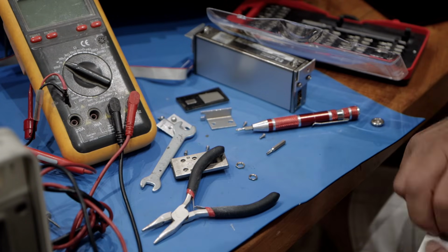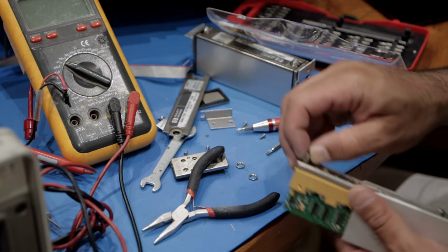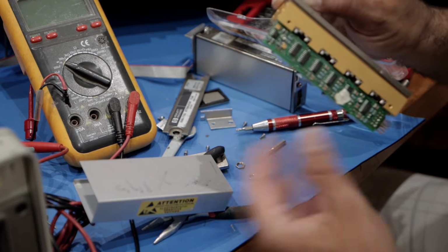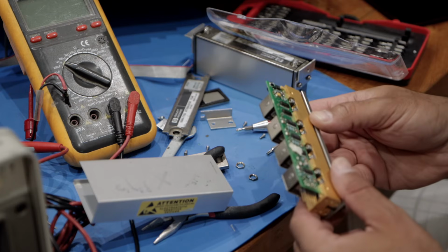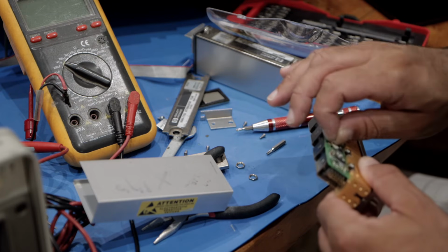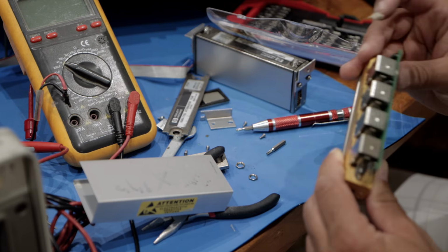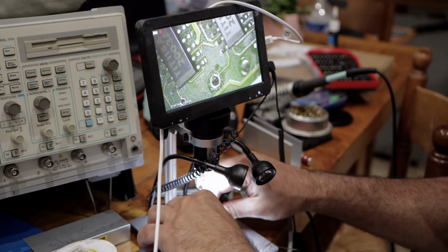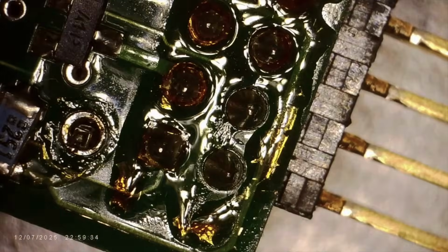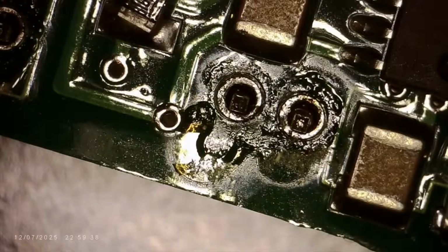Okay, now that I've removed the side and upper cover, I can pull out the entire attenuator assembly to have a look at what's inside. Wait a minute, what is this? A sticker over one of the ICs. That's never a good sign. This IC might be faulty. Let's take a closer look under the microscope. Now I see why I couldn't hear any clicks. The electronic board is completely disconnected from the solenoids.